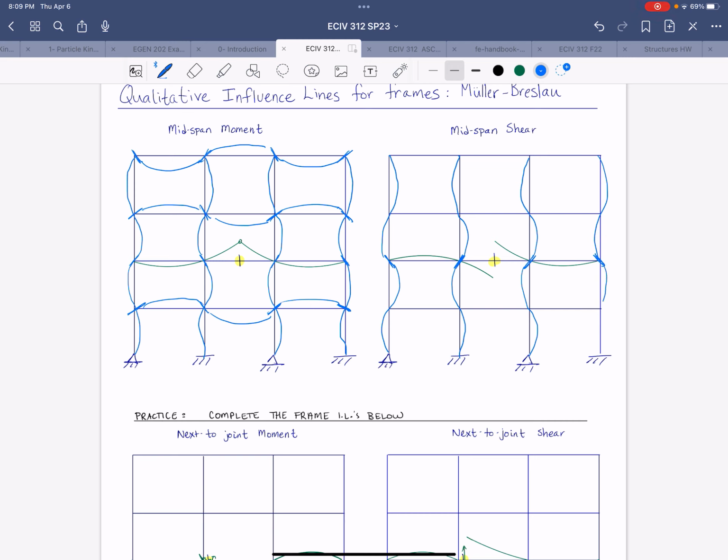All right, and whether your displacement is positive or negative for a beam, to the left or the right for a column. So what we're going to find when we do the beam influence lines then, and I'll just draw the top one, is that in this center span, which aligns with the location where we cut the beam on one level, we now have the columns rotating in the same direction on either side of that span.